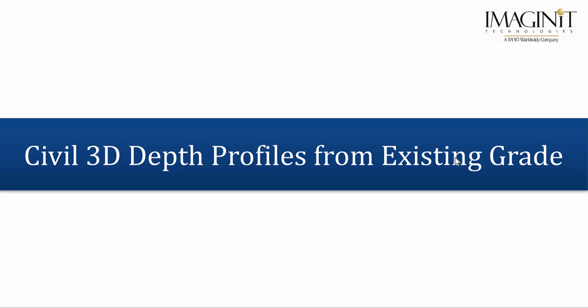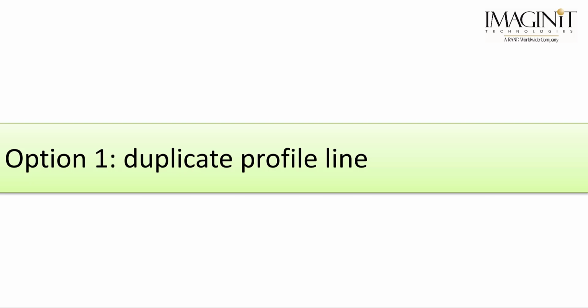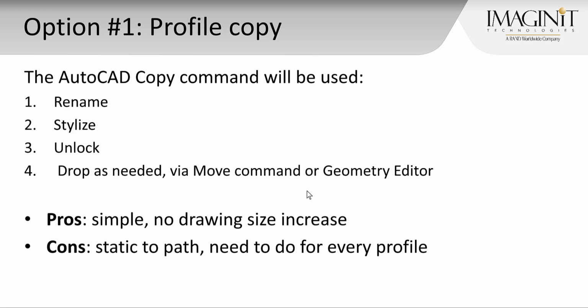In this video, we will be exploring how to create depth profiles from an existing grade surface via two simple options. First, we'll explore option 1, to duplicate the profile line. This can be done via the AutoCAD copy command.